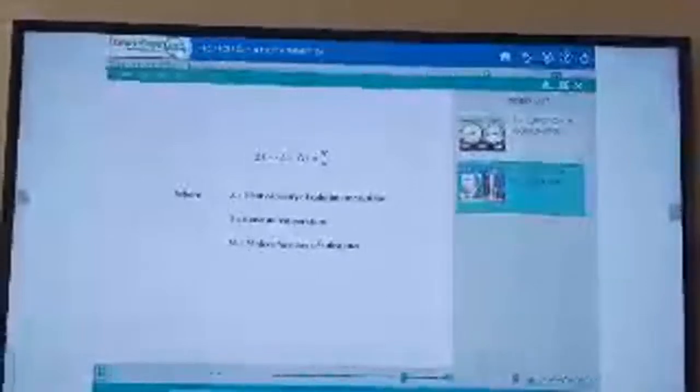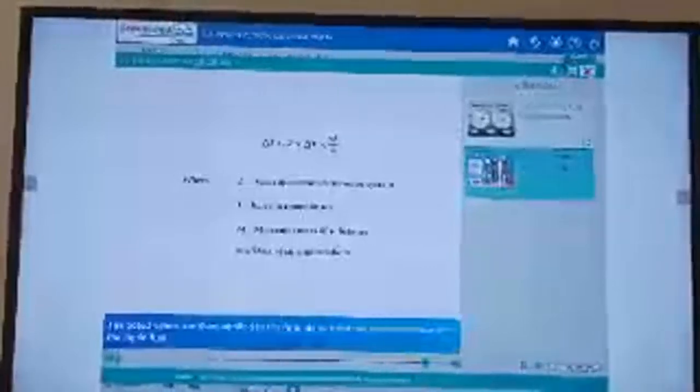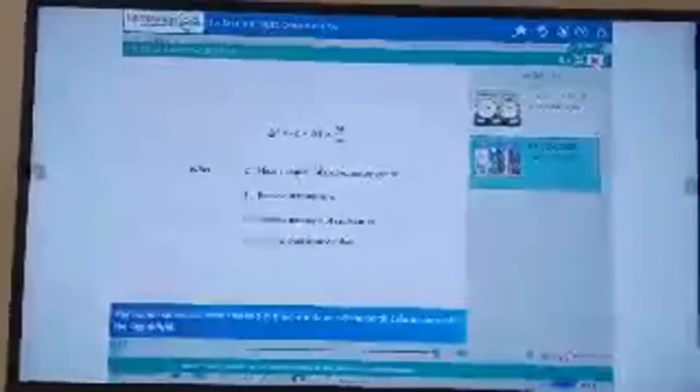Delta E is equal to minus Z into delta T into M divided by W, where Z is equal to heat capacity of calorimeter system, T is equal to rising temperature, M is equal to molecular mass of substance, W is equal to mass of substance taken. The noted values are then applied to the formula to calculate the calorific value of the liquid fuel.